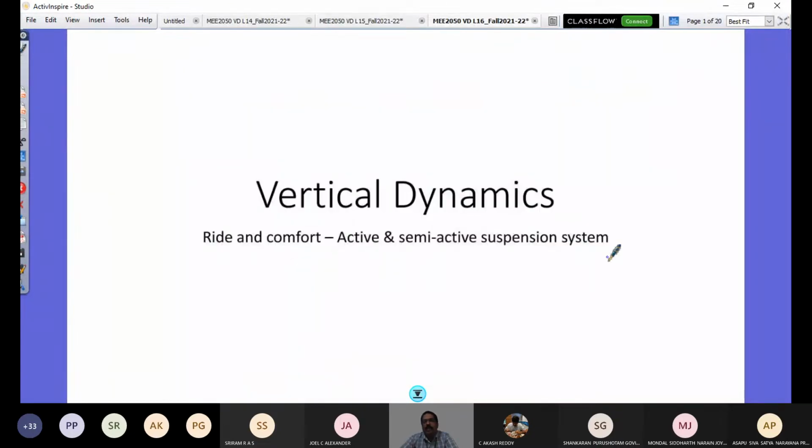And you have got a thorough background to understand this, as you now know deterministic vibration models of your vehicle, and how you go about understanding the vehicle nature and its amplitude ratios and so on. And you also now know thoroughly the background of enforcement of standards that put pressure on OEMs to work on the vehicle design so that you get a good ride. And we also have characterized importantly the road profile through its power spectral density function, and we looked at its application through the simplest case of a single degree of freedom model.